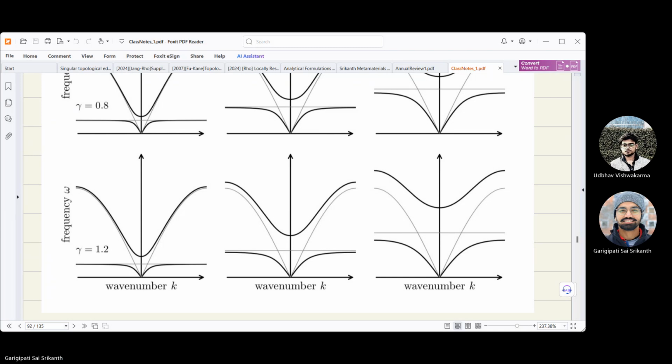So in a way, everything is local resonance. Even your spring will have some mass and it'll also have some internal resonances. And that way everything is local resonance. But if those local resonances are very high, everything is Bragg. So it depends on your frequency of interest what is local resonance and what is Bragg. If within your frequency of interest you have some particular attenuation profile, some particular modes, then you classify it as local resonant, Bragg, such things.